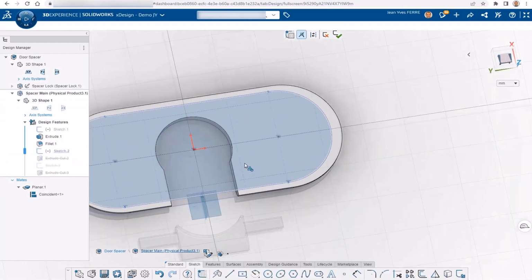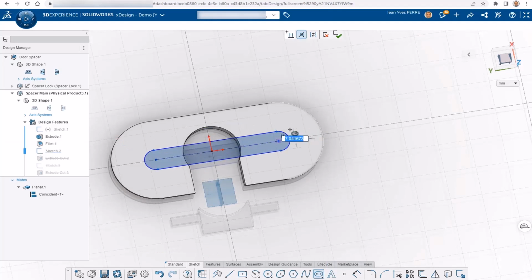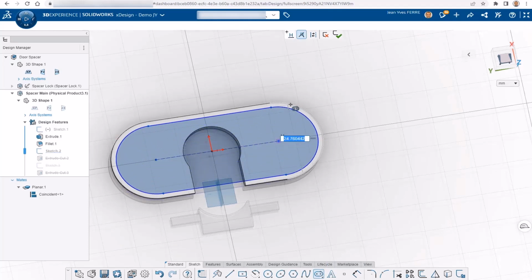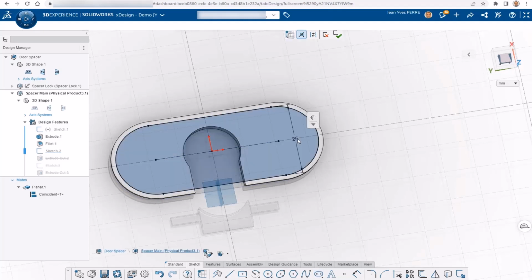This is due to the mistake I mentioned earlier when I left the blue contour in the sketch. As sketch entities are not constrained, they can move freely. Therefore, I start over with a sketch slot that I lock this time on centers. See how I make the center of this circular shape visible just hovering on the part edge. Once the value is entered, sketch turns black, so now I know it's fully defined.